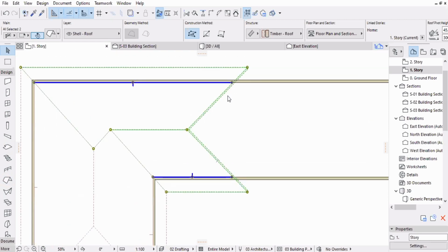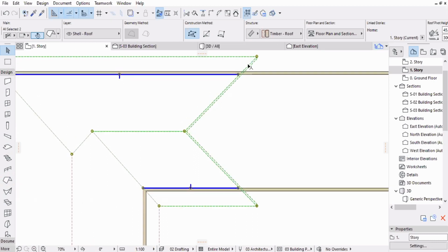But things might look accurate here as you're moving the nodes around. You might draw an accurate triangle in plan in this triangular portion, drawing a lean-to roof using the polygon command. You can draw a lean-to roof using this shape, but mind you, these edges will never be joined. It will never be joined. There will always be gaps.